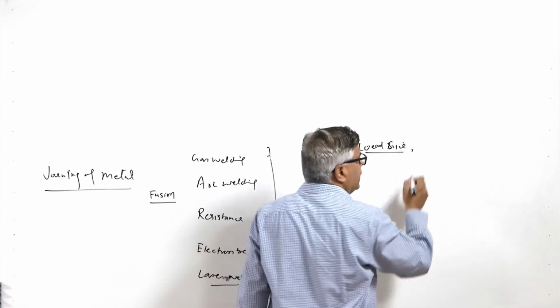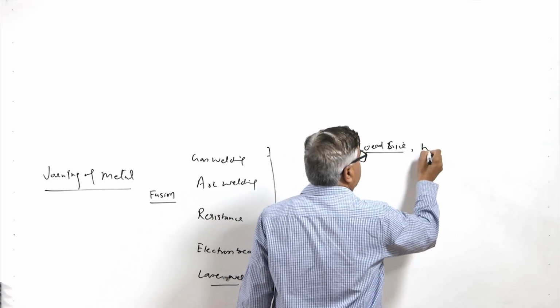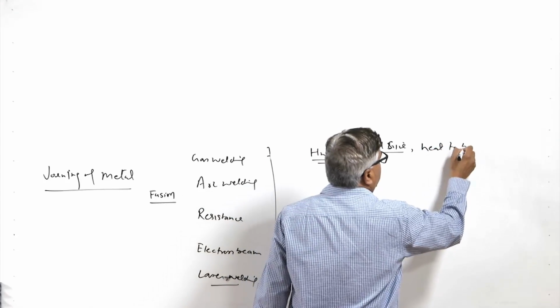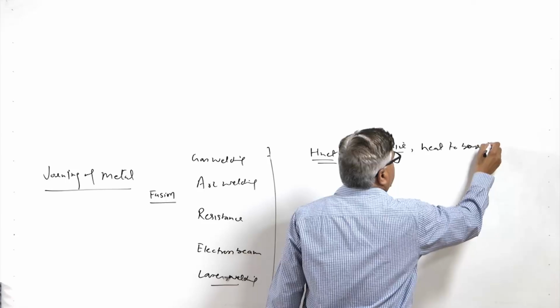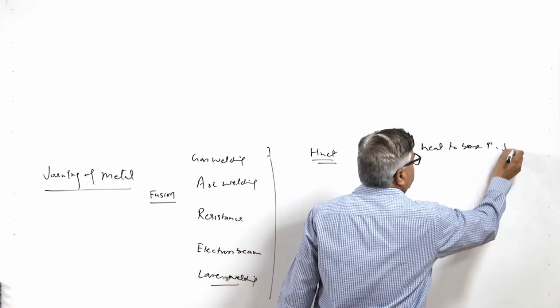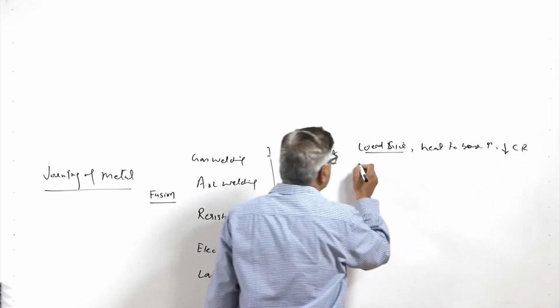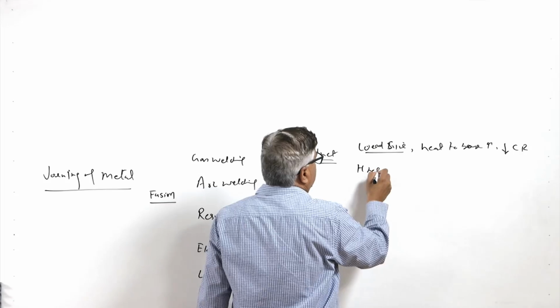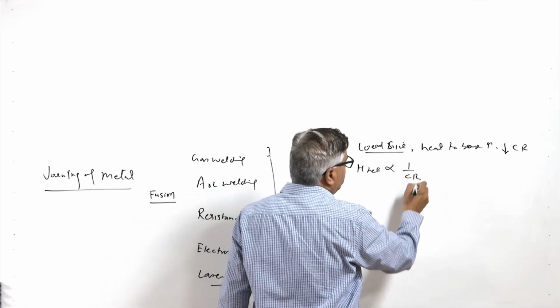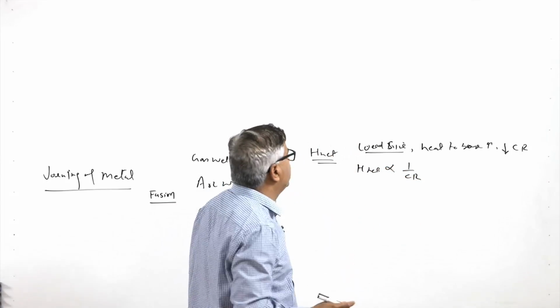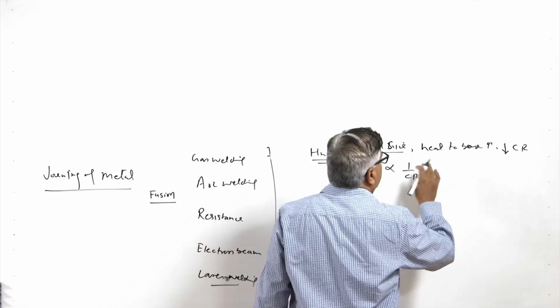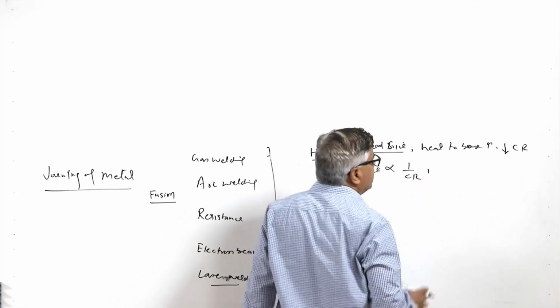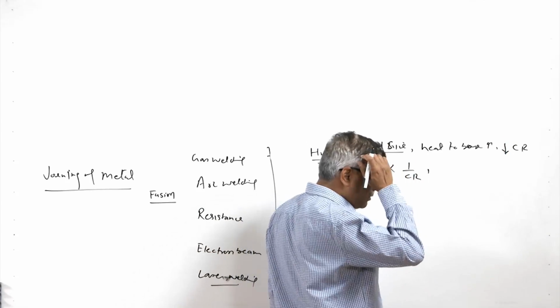The amount of heat delivered to the base metal also increases, which in turn reduces the cooling rate. In general, the heat input H net is inversely proportional to the cooling rate experienced by the weld metal, because of the greater amount of heat being supplied to the base metal below the fusion boundary.